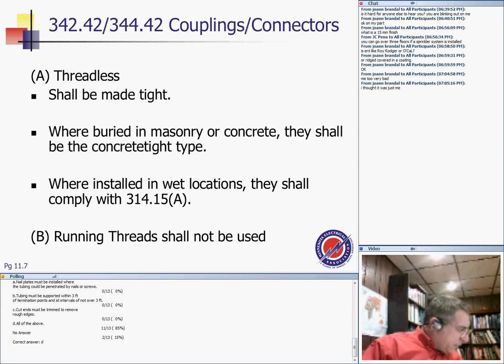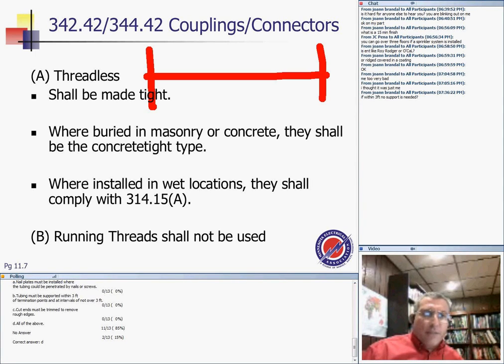Another thing is I'm going to go directly to rigid. The use of rigid has a table. Up to 3/4, every 10 feet. If your conduits are 3 or larger, they allow 20 feet. If you have a rigid conduit 3 or larger, you can go 20 feet between the supports. That's for rigid metal conduit. It's very important. You can go 20 feet, guys.